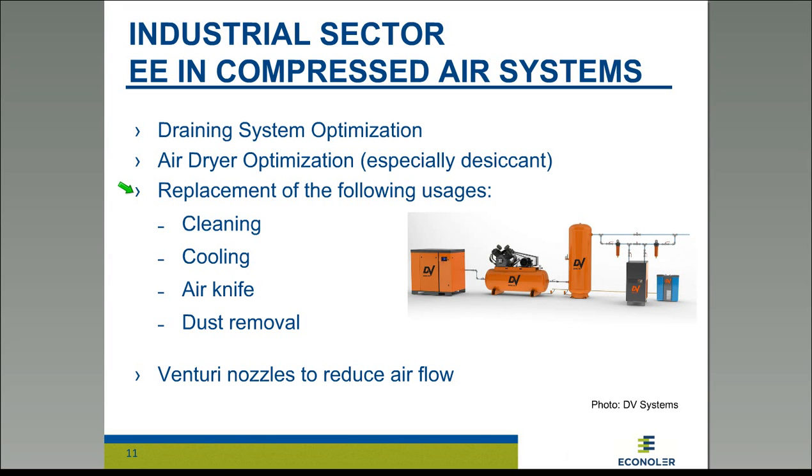I did mention that there is very often in industry usage where compressed air is applied to wrong end usages, like cleaning, which is really quite an expensive way to clean space and equipment. It's used also for cooling of components. It's used as an air knife for oven and for dust removal. So that's another cleaning application. And what we have found in several industries, we can reduce by 90% the energy required for cleaning or dust removal application or air knife by using other types of techniques, but not compressed air. If you still have to use some compressed air, it's very often interesting to consider using a venturi nozzle instead of using system pressure to create nozzle and airflow.